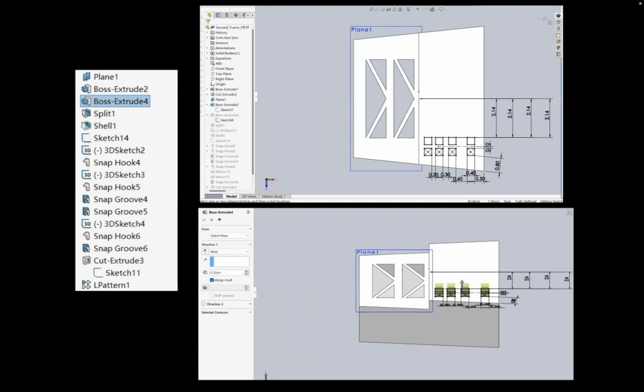And we're using the mirror entity to make the second row of hooks with the central line 0.1 centimeter away from the first row of hooks, because the distance again matches the diameter of the elastic cord. We extrude up 0.3 centimeters, which provides more space for the crossing of elastic cords. Some elastic cords are perpendicular to the others, so they will be crossed.